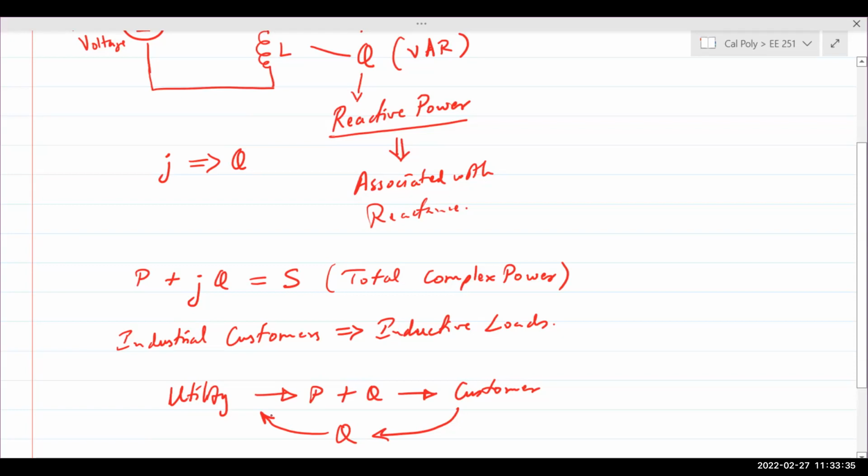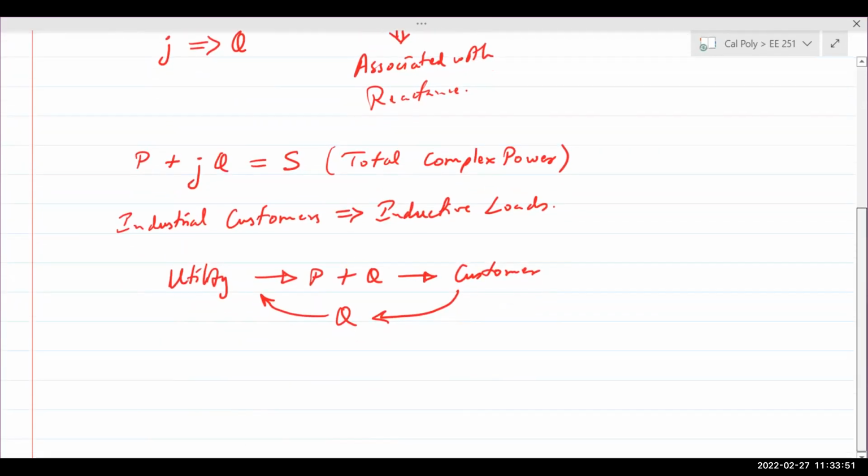It is important to remember that reactive power is not doing any real work. The real work is done by the average power, and hence it is also known as real power. So the reactive power, even though it is not doing any real work, still has to be transmitted over long distance transmission lines. And that is not desirable. Anytime you have electrical energy transmitting over long distances, the wires and the conductors heat up and there is tremendous loss of energy.